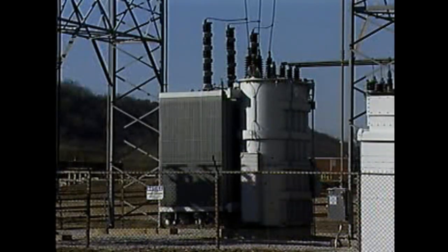In the arrangement illustrated here, there's a natural circulation of oil. As the oil picks up heat from the windings, its density decreases, causing it to rise. The warmer oil enters the top of the radiators, where its heat is transferred through the radiators to the surrounding air. As a result, the oil becomes cooler and more dense. The cooler oil sinks to the bottom of the radiators, then re-enters the transformer, where it can pick up more heat from the windings. Some oil-cooled transformers use mechanical devices to aid in cooling.